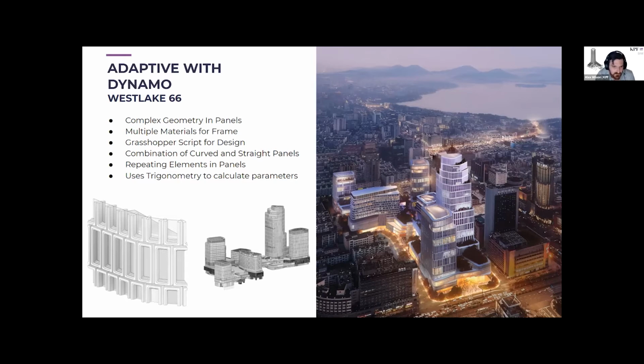These adaptive panels are vertical. So they're 4-point and 6-point. What I mean by 4-point panels is there are 4 placement points for the panels. And the reason for introducing the additional 2 is to create an arc. So if your panel is curved, you add an additional 2 points. So, between the bottom and the top, there's an additional point, which pushes in and out to control the radii.